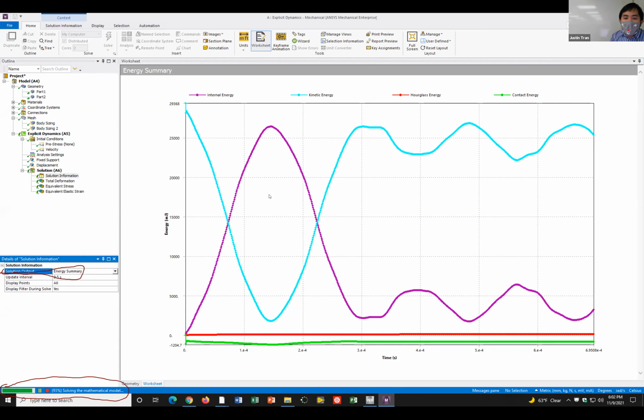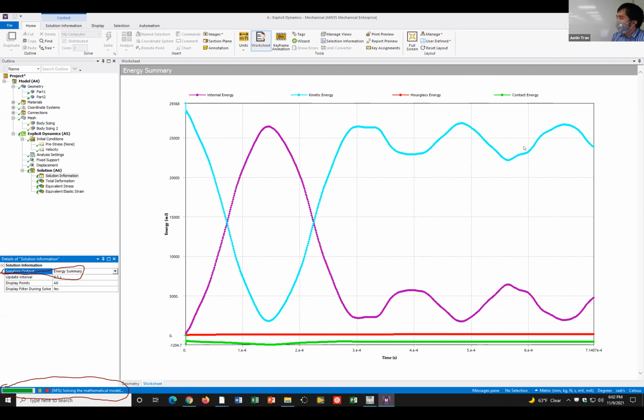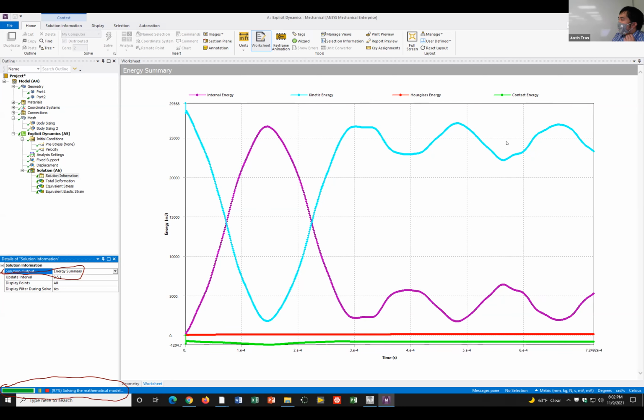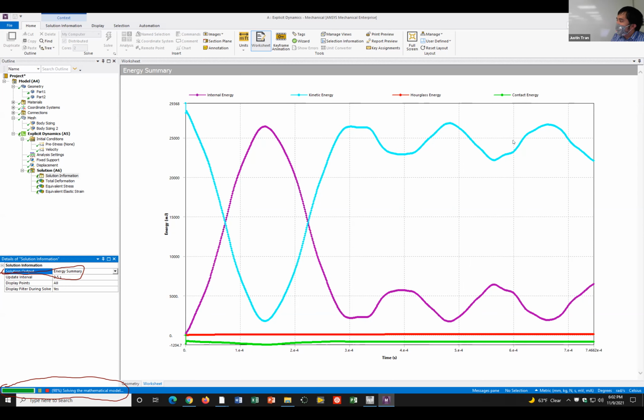I would say after this point right here, the simulation becomes a little less realistic, because normally you would expect the car to buckle and just stay deformed. But because we're using a linear material model, linear elements and all that stuff, the car basically acts like a spring.